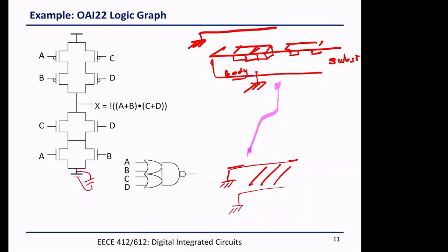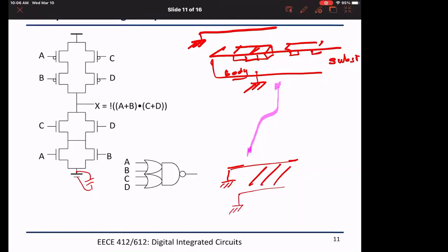In a similar way, since the NMOS is connected to VDD, and since VDD is also considered a DC signal, which is strong, we typically do not calculate the parasitics between VDD and ground or between ground and ground. We ignore them. Now there is much more in-depth analysis here. I don't want you to worry about it. But I want you to think that just like we studied small signal analysis in 311, I do not study parasitics on VDD and ground.